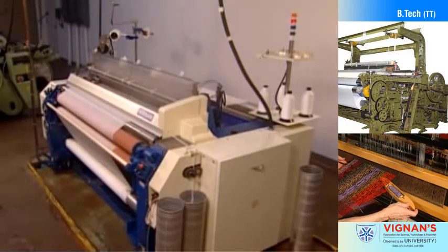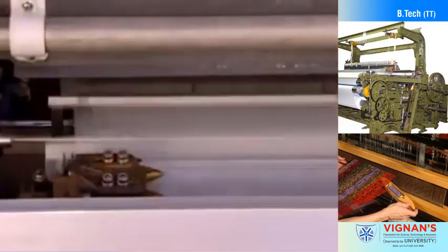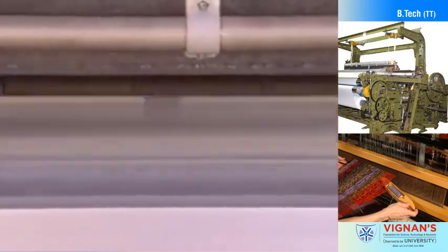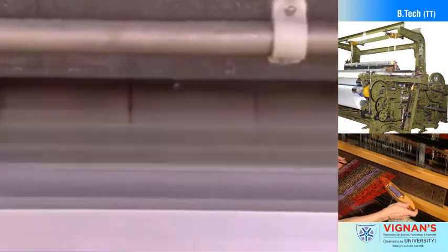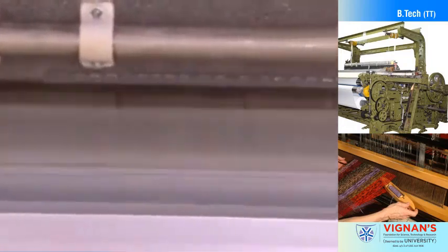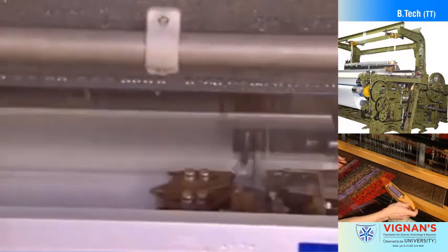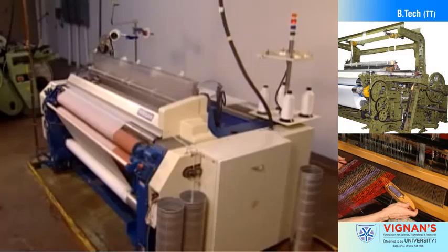Water jet filling insertion uses the same concept of filling insertion as the air jet. Water is used instead of air to project the filling yarn across the warp shed. Due to the higher density of the water jet as compared to the air jet, booster nozzles and profiled reeds are not needed. Speeds of water jet insertion rival those of air jet weaving. One shortcoming of water jet weaving is that only hydrophobic fibers can be used.